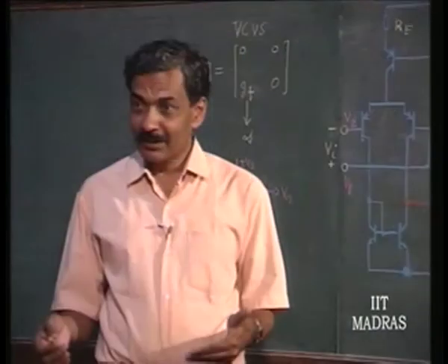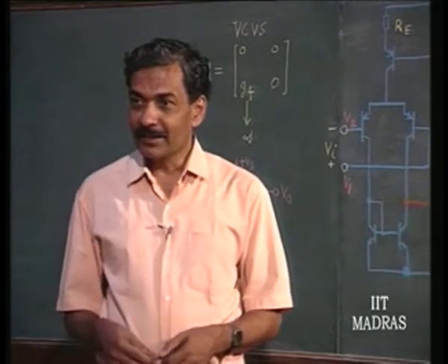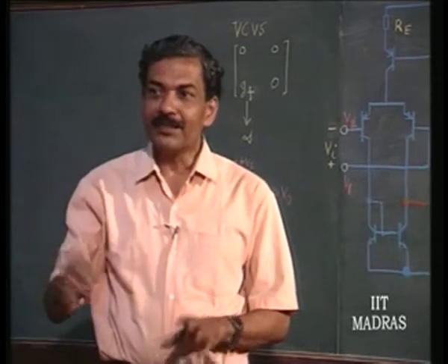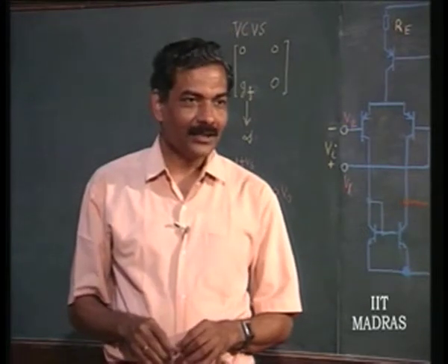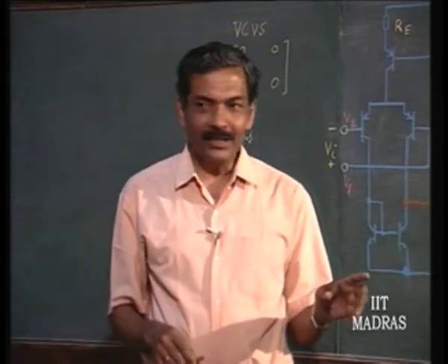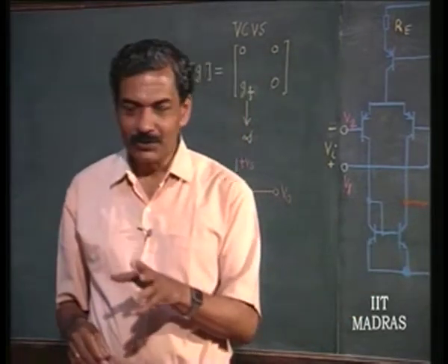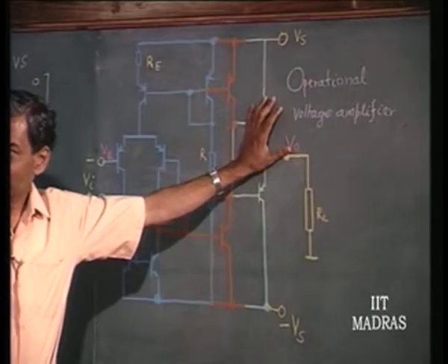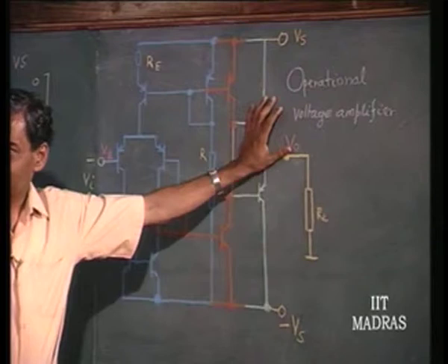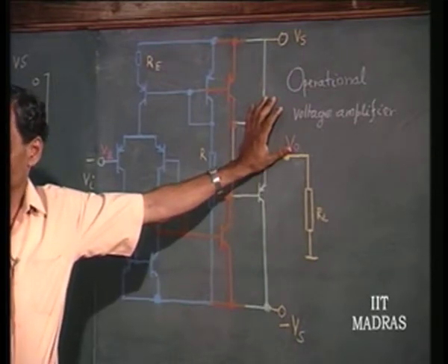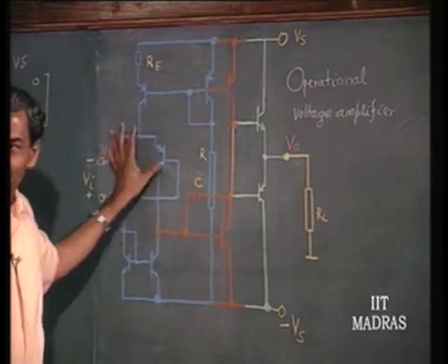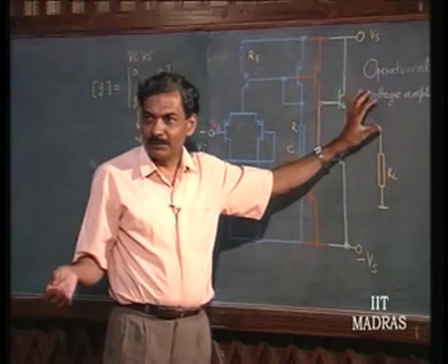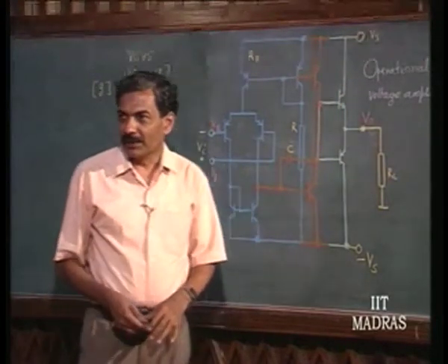It will give you gain, okay, and can also act as a decent output stage, giving you almost the full swing possible, and it is automatically short circuit protected because it is actually operating in the current saturation mode, and therefore, this is how we can come up with a sort of BiMOS op amp. Okay. Input MOSFET stage, intermediate bipolar stage, and output could be a CMOS inverter stage.